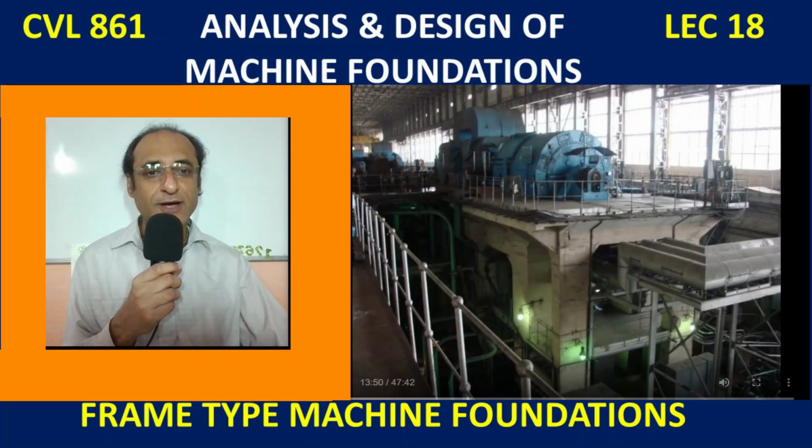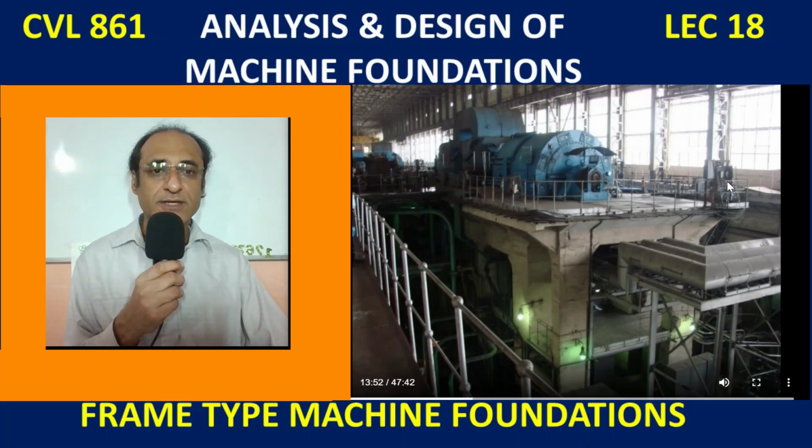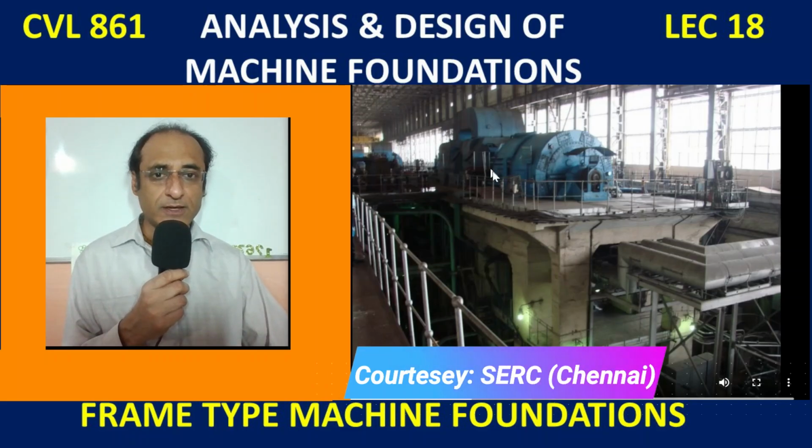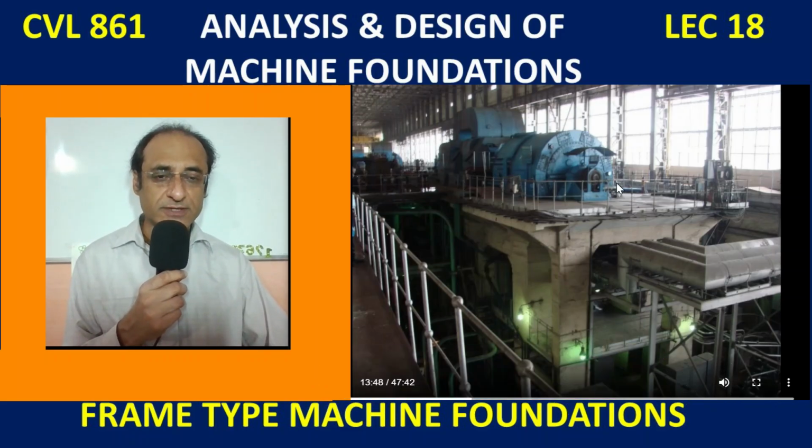So now this is how in a real life situation the deck and the entire system looks like. It's a very massive structure. Here you can see the machine, also the turbo generator. I'm just pausing the video here. What you can see here, the shape is such that it supports the machine. The bearing points and all those locations are predetermined in design, with data provided by the manufacturer, and it has a lot of utilities also, so that the machine can be serviced.